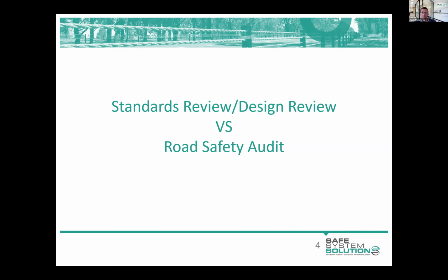When you're doing a road safety audit, you really are focused on the road safety implications of a design. If something doesn't meet a standard, you need to think about, is it safe? It's often the case that a standard is not met and it may not have an associated safety issue. Conversely, a standard may be met, but there still may be some safety issues there.